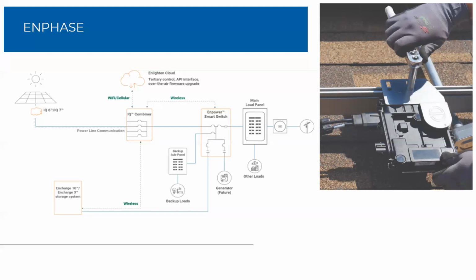There's a chart that I reference almost daily with the maximum amount of microinverters that you can pair with a given battery. So similar to our PV inverter, hybrid inverter relationship, we also want to consider the amount of micros that are feeding our N-Charge system. I don't have it memorized, but off the top of my head, let's say we have 20 IQ 7 pluses. That might equate roughly to a single N-Charge 10.